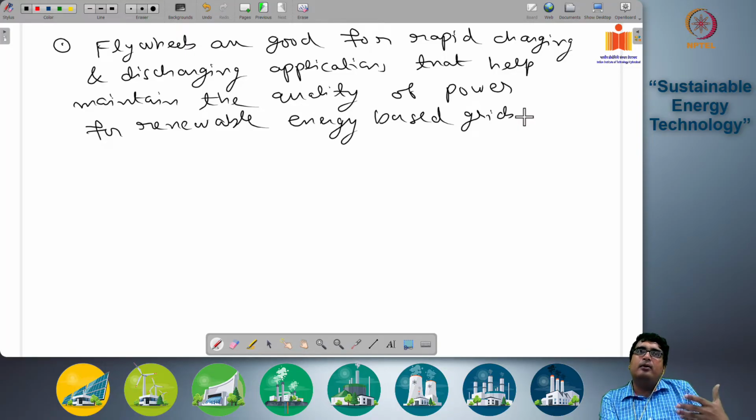When supply is high and demand is low, you are connecting the flywheel shaft to the generator shaft to transmit some of its rotational energy quickly to the flywheel shaft, where it is stored for a certain period of time, usually a short period of time.